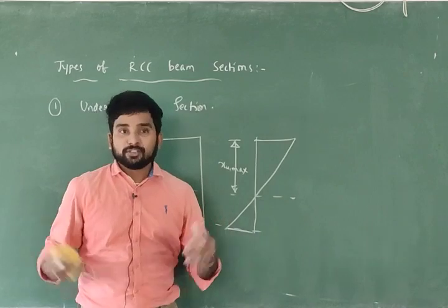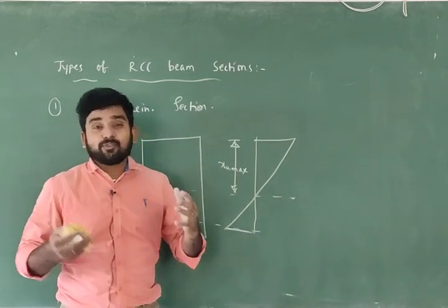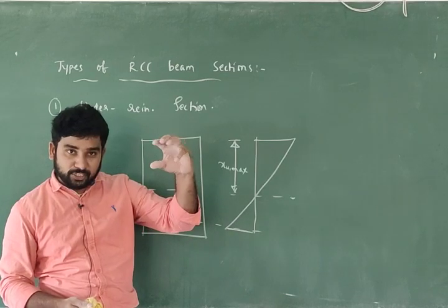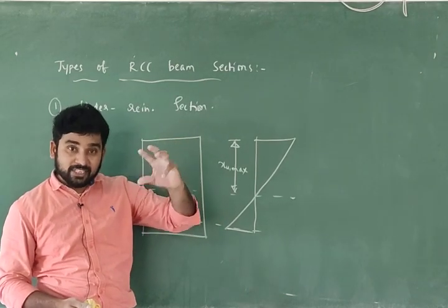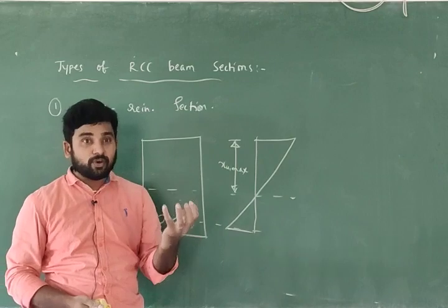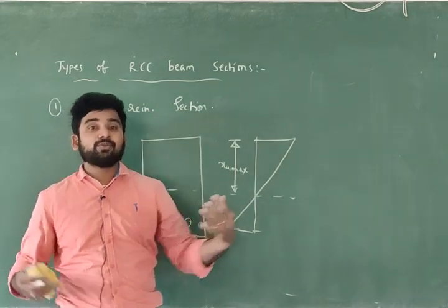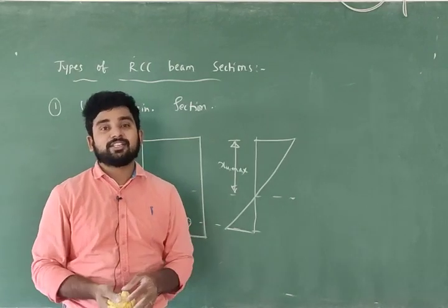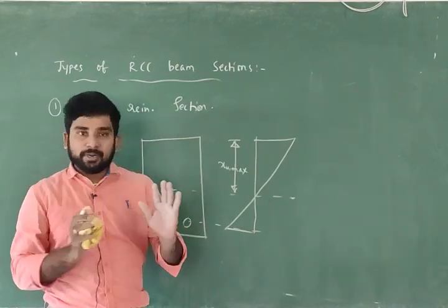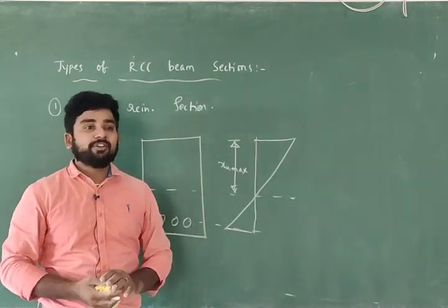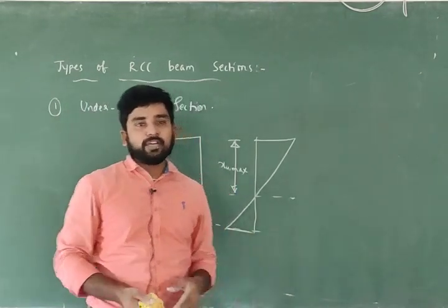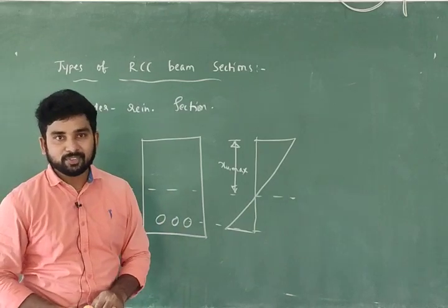So that is a warning. If steel reaches its permissible value, there is no problem, because steel is a ductile material. It will give warning so that we have time to escape from that structure. It is not a single day or single minute. It will take time, but we can understand that this structure will collapse in maybe a few days or a few months. Okay.